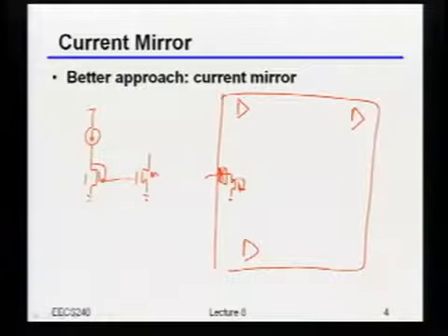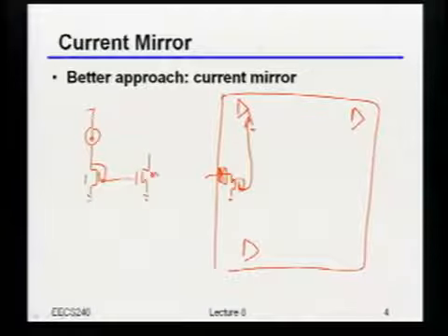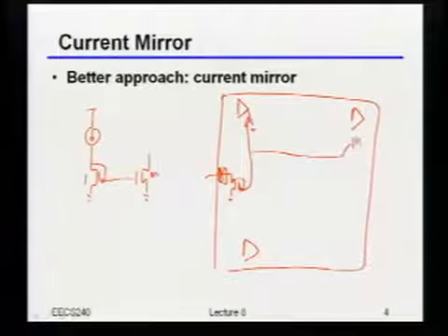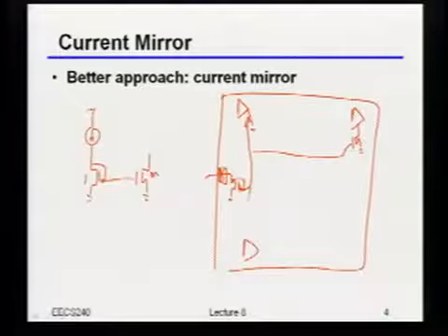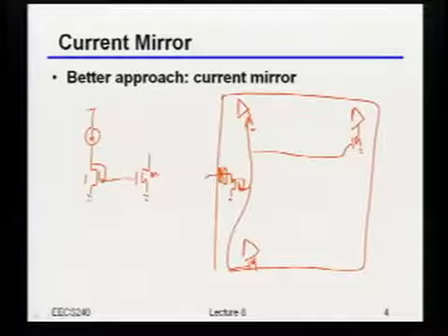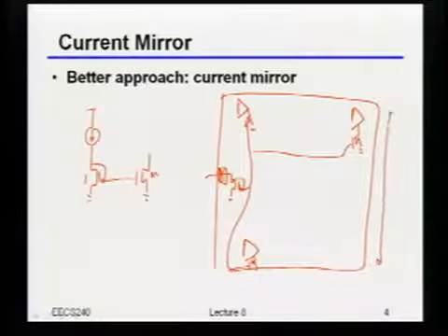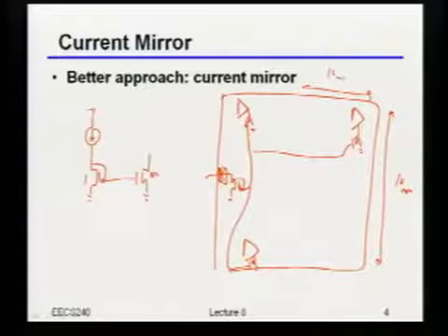So how about I just take that wire and put all of the current mirrors locally at each amplifier where I actually want to use it. I'm just going to take that voltage and distribute it to the gate of all those mirrors all over the chip. And just to give you an idea, this is maybe 10 millimeters by 10 millimeters.